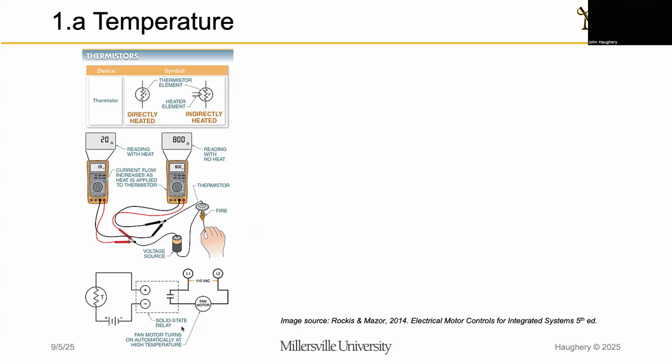When I apply a voltage to the transistor, it energizes, quote unquote, the transistor, allowing the output to conduct or not conduct, or to be open or closed, kind of in the mechanical relay terminology. And so a thermistor is just going to drive or control the input of our solid state relay that then determines if the output is either open or closed, that then actually controls the device or the load that we're considering.